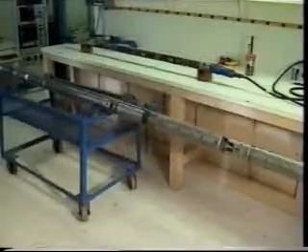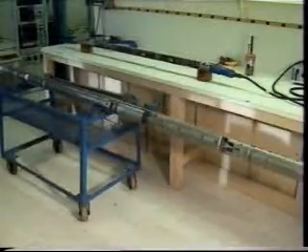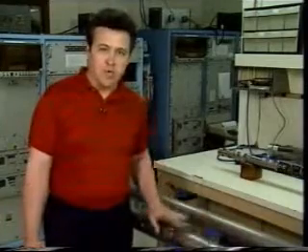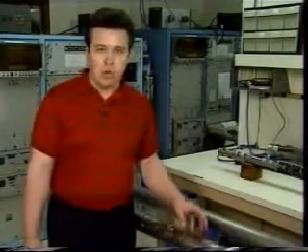This device is called a lithodensity tool. This other device, typically called a neutron tool, has a neutron source and detectors from which porosity determinations are made. A nice feature about most of these devices is that they can investigate beyond steel casing, a capability electrical logging tools do not have. Let's begin with a simple gamma ray tool and its modern specifications.